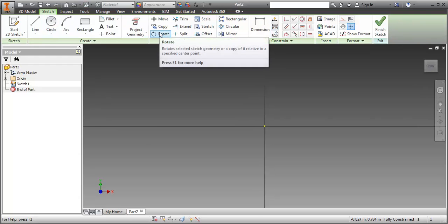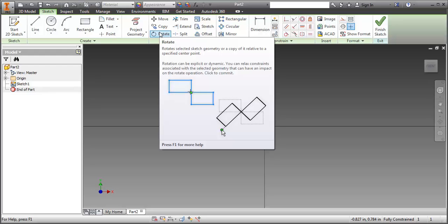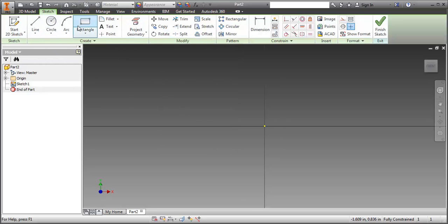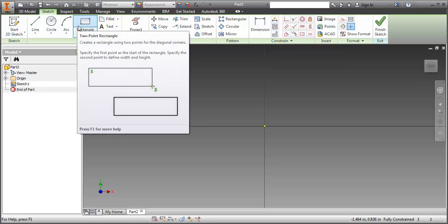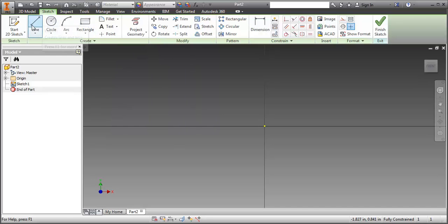Alright, these are the line drawing tools, just like in 2D AutoCAD, you can draw lines and circles and arcs and rectangles. So when you create a sketch, you don't worry so much about the dimensions, but I would be more concerned about the proportion of the sketch. So I'm going to draw this sketch of the adjustment block and just take a look at what I draw. I'm going to draw a line at the bottom, and the length of it is 4 3/8, but I'm just going to draw it roughly 2 inches, and then I'm going to draw it up, kind of like that, and over.